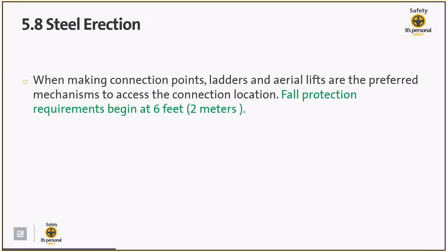When you look at section 5.8, which focuses on steel erection, the requirement for fall protection to begin at 6 feet is a requirement that's above OSHA regulations.